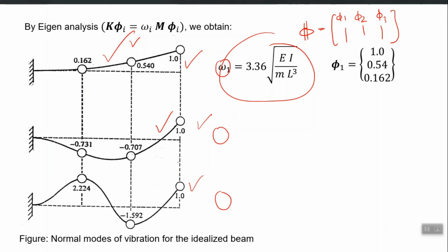So just imagine a structure and you shake the ground. The first mode shape naturally will dominate the response, right? If the building is regular and typical. I cannot say that it will be true for all cases, but mostly the first mode shape has the highest contribution. If you quantify in terms of amplitude, you can say 60-70% of the displacement response is coming from first mode, 20% is coming from second mode, and maybe less than 10% is coming from third mode in one particular direction. When I say first, second, third, I don't mean the software numbering. I mean first mode in X, second mode in X, third mode in X, right? So first three modes I mean in one particular direction.